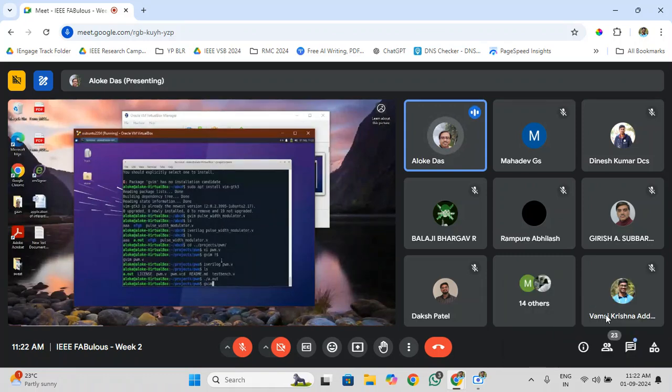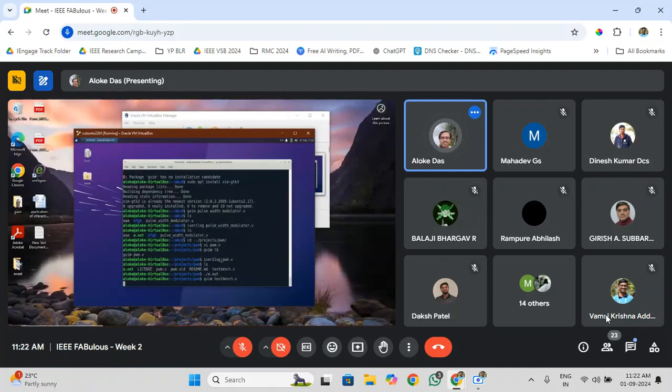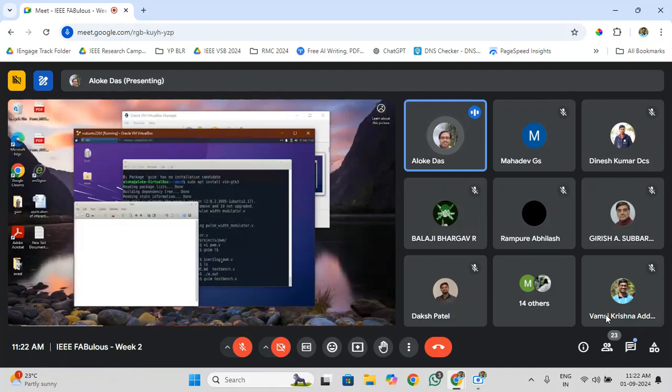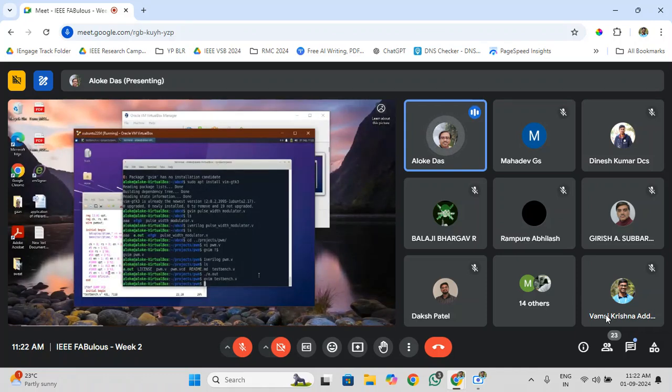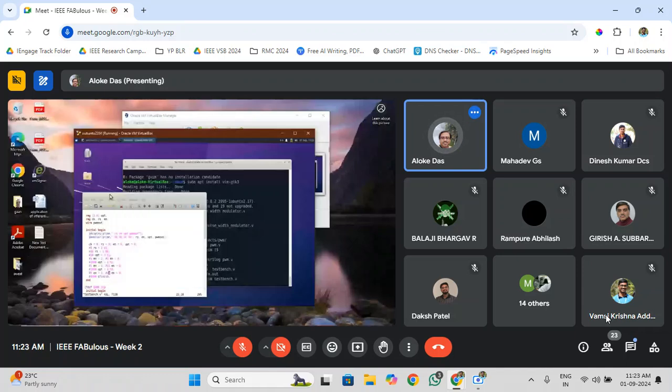always for any design. That is the infrastructure you have to create, your design and your test bench. And this is a small design, so it fit in only one file, but a design can be multi-file also. Then, if your design spreads across multiple files, all the files should be listed after iverilog to get a successful compilation. And this is the test bench.